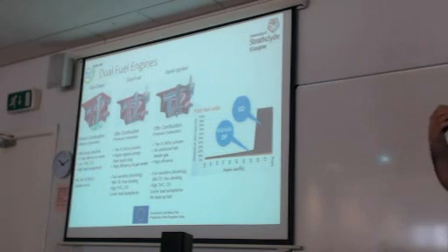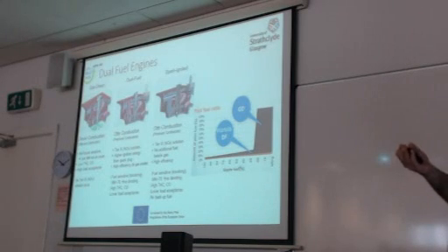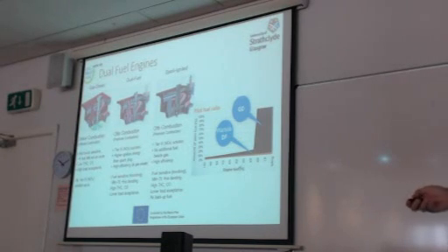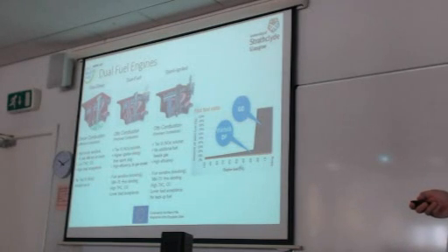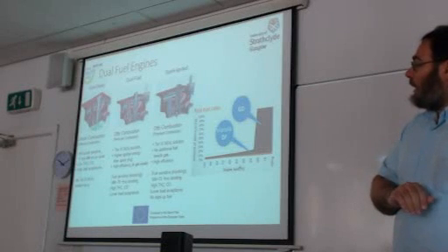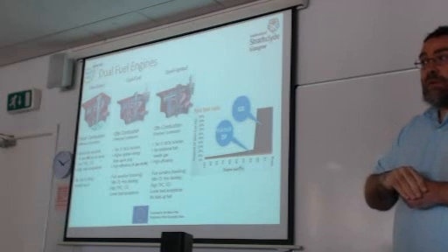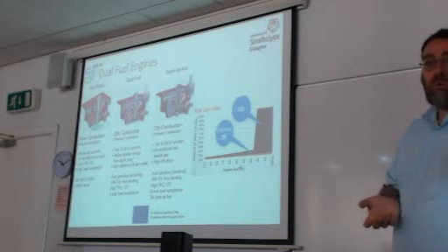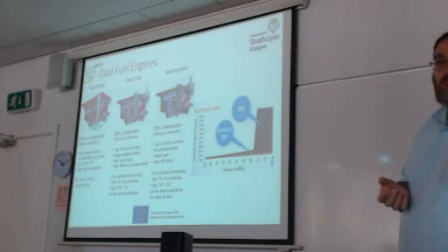Another important parameter of the fuel is the methane number, and methane number is not an issue in this case. As I mentioned earlier, various LNG types contain various amounts of methane, from 87% to 95%, and this characterizes the methane number of the fuel. The hydrocarbons and CO are low. Why? Any explanation of that? So why, in the case of gas diesel engines, are the hydrocarbons and CO, carbon monoxide, low?